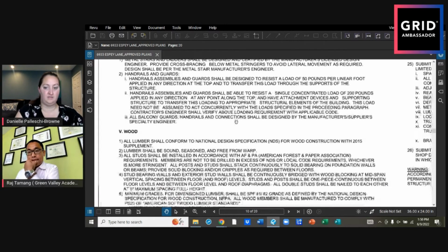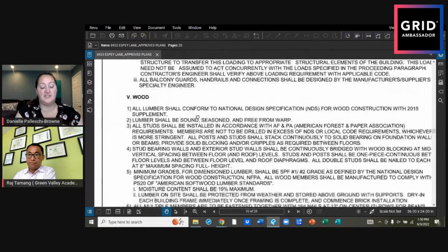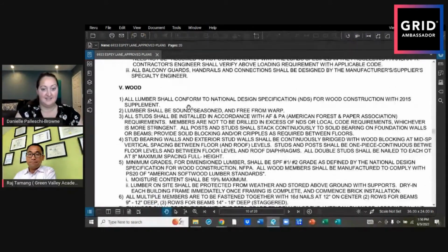Got it. Now that makes sense, because they said they were probably going to have to cover it in plastic, since they're pouring this in 2 weeks, which is almost July. And it's hot here now, almost 90 degrees for almost a month. So they're going to cover it and keep it moist to help it maintain or improve its strength and structure as it cures. Correct.